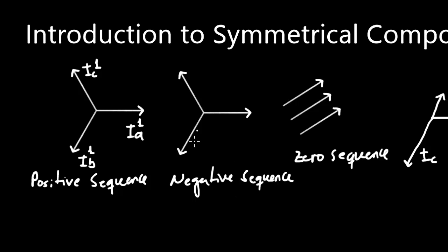And then on the negative sequence set, we're going to have a phase rotation that is opposite to what our system is. So for this example, I'm assuming that the system has an ABC rotation. So let me write it over here. This is our assumption for these vectors over here. We have a system that has an ABC rotation. And so the positive sequence set has the same rotation as the system under normal conditions. But the negative sequence set has an opposite rotation.